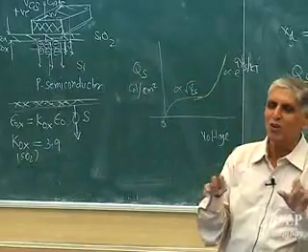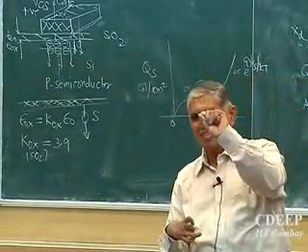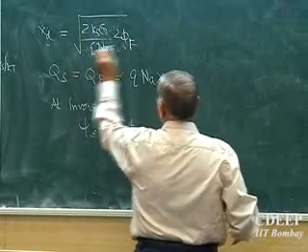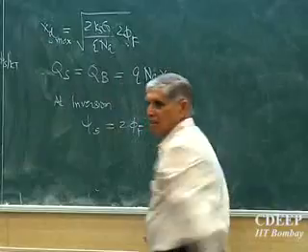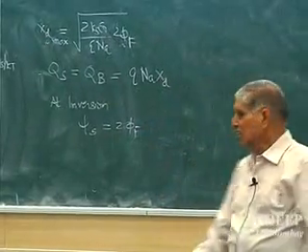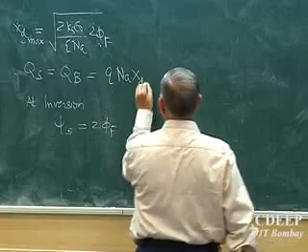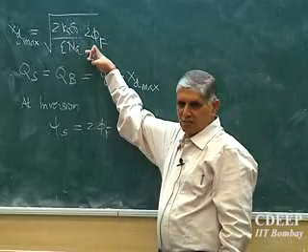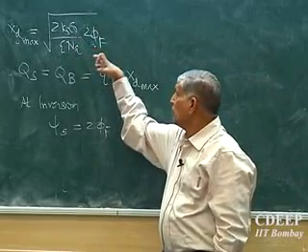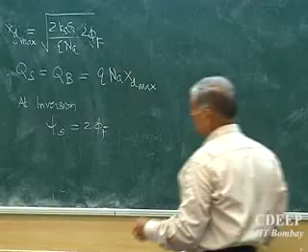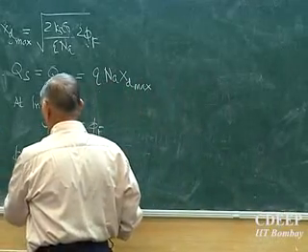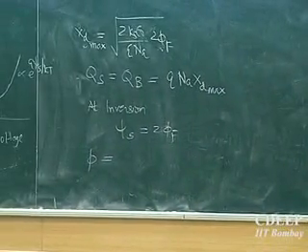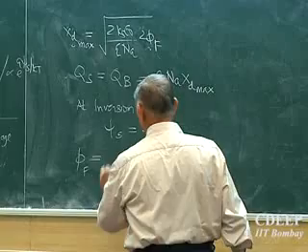So to compensate, we don't want to do theory, we say okay, at this time when this becomes 2 phi f, the depletion layer will reach maximum, and the maximum bulk charge, which then should be this, where xd max is given by this. Is that correct? So 2 phi f, okay, what is phi f in terms of concentration from the Boltzmann relation? Phi f is EI minus EF. So what is phi f in our case?